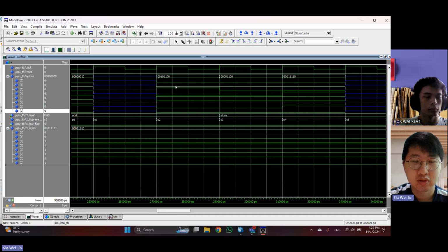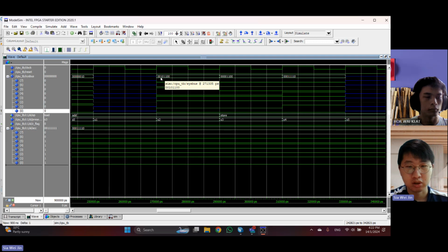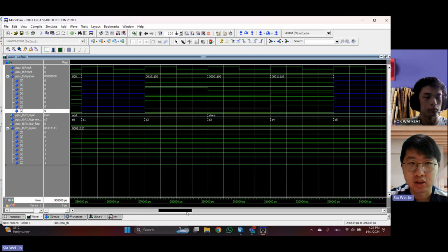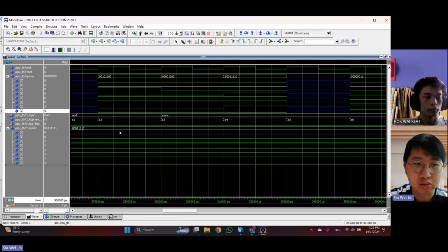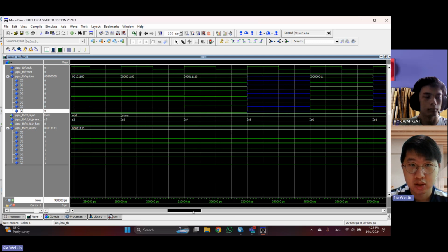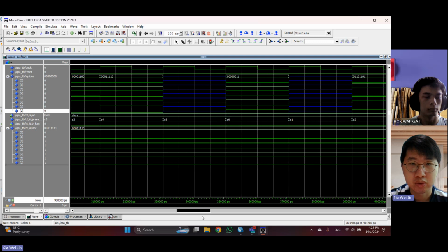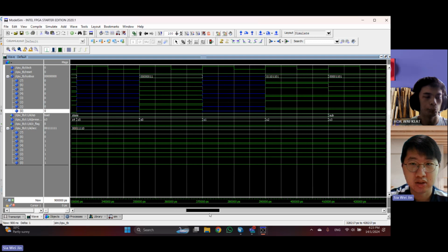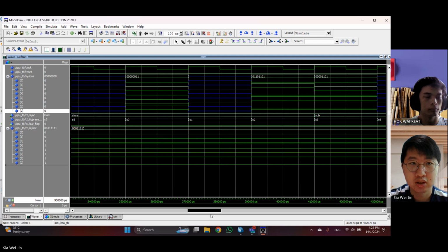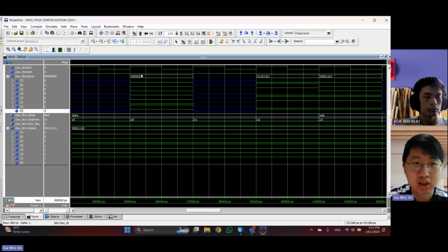Then moving on, the next instruction is 001, which stands for store, and we'll be storing the content of the accumulator inside this address, which is 0C. And moving on forward, the program counter increments by 1 again. Okay, so we've got 3 right now.